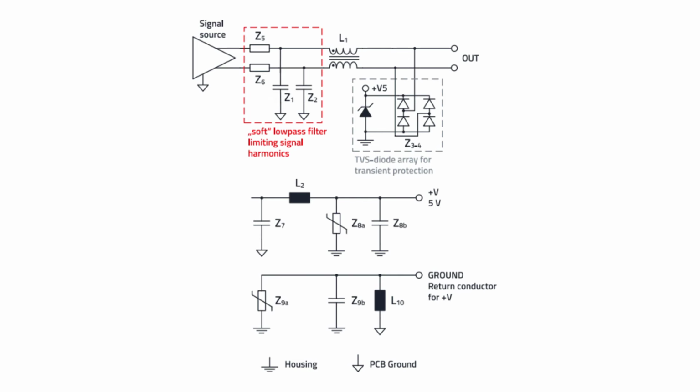An example of a suitable capacitor for this is the WCAP-CSGP. This is a generic ceramic capacitor, and for a varistor, the WE-VS surface mount varistor. Z3, Z4 are TVS diode arrays, transient voltage suppression arrays, such as the WE-TVS diode 824013-6 from the high-speed series, and they're used to protect signal lines against transient voltages.